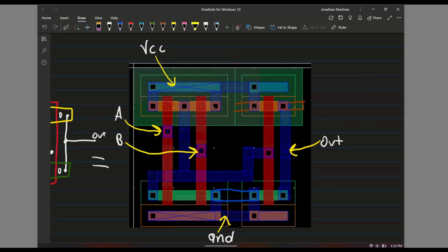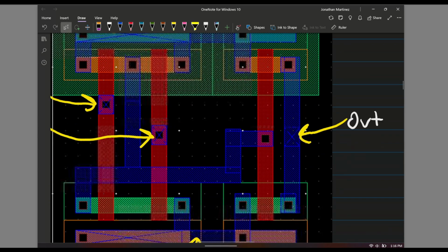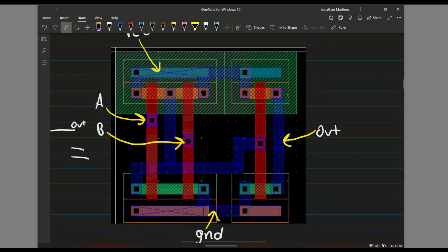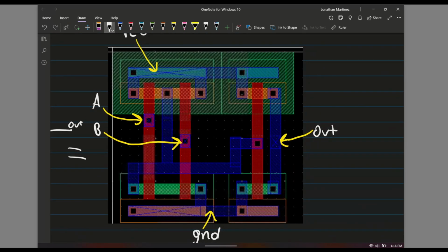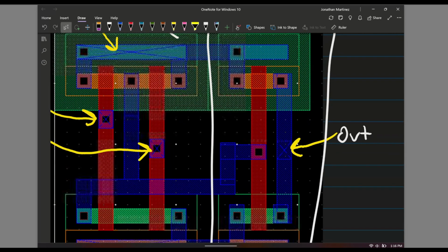So right here, if I can draw it out too, right? I can create another file. In fact, this is what's so interesting about this. I can create another file and call it my AND gate. In that case, I would start optimizing that specific file. Some things that I would do is probably move the entire inverter to the left here. So I would take all this and bring it over to the left a little bit, because I see some space that is not being used here.